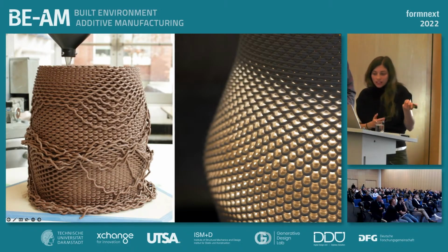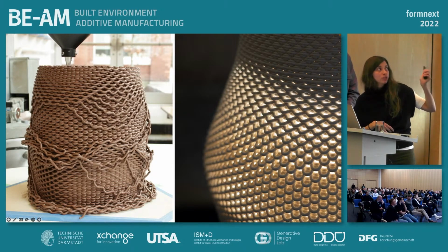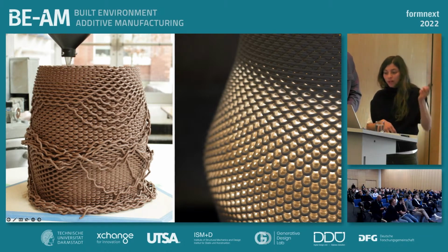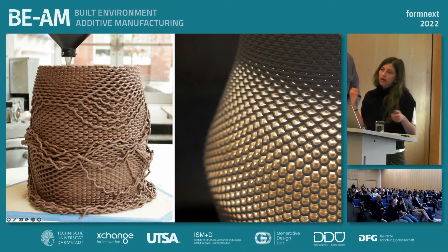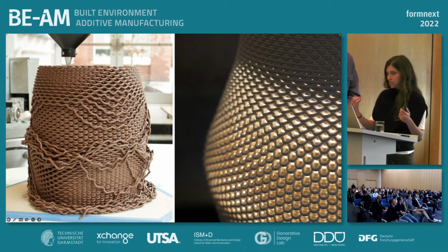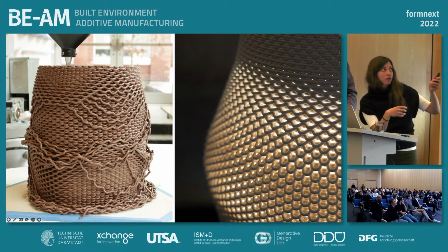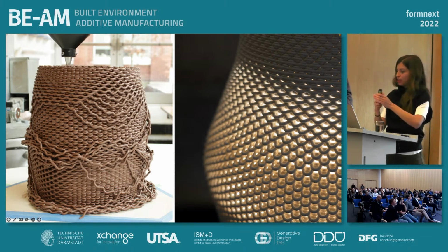So the amount of sag in each aperture has to be pretty carefully controlled in order to prevent structural collapse. The image that you see here depicts a prototype actually being printed with a different type of clay body called earthenware, but using obviously the medium typology's printing parameters. Because earthenware doesn't really have the same plasticizers or the same viscid, meaning kind of sticky properties as the stoneware, it starts to delaminate. So it's kind of this very behavior that I was just explaining where the exterior skin is pulling from the interior.